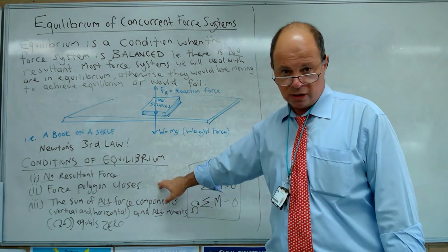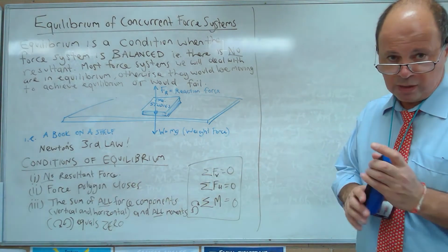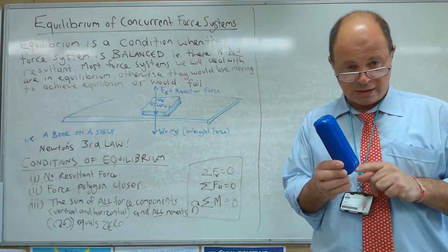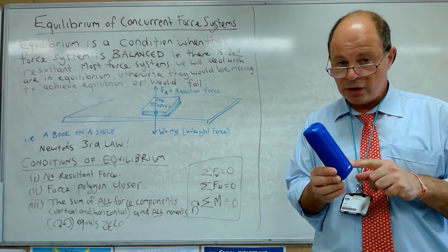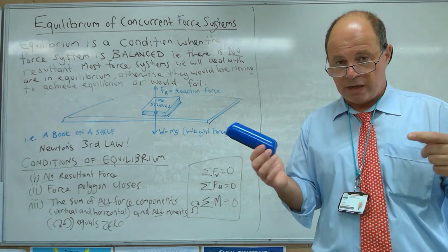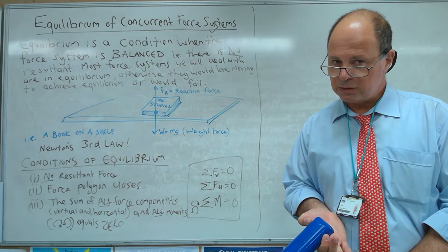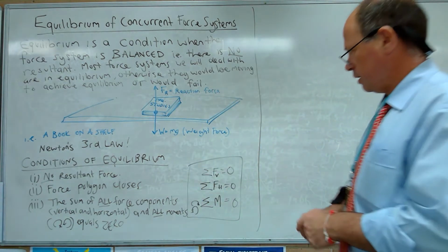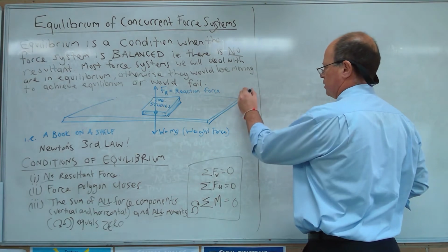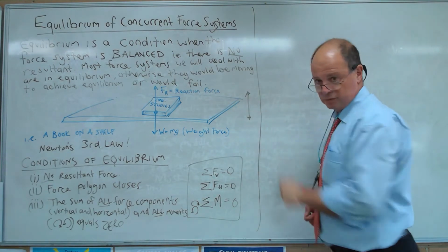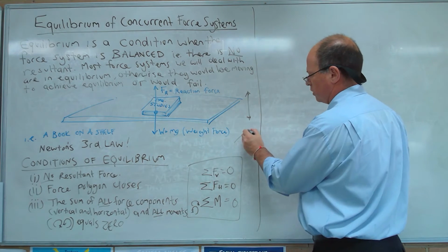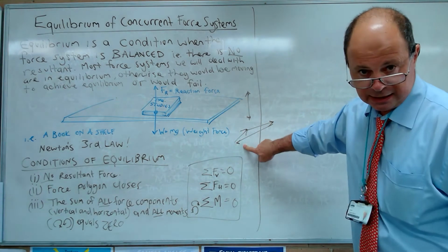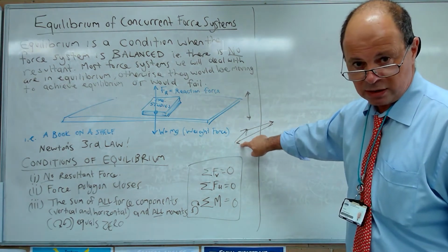The force polygon closes, so when we add our vectors, and we've done addition of vectors, you will return to the starting point when you add them. If you don't return to the starting point and the system is in equilibrium, it means you've missed a force, okay? So in this instance here, one goes up, tip to tail, one goes down, and therefore the system is closed, okay? If you had a more complex system where you're adding, if you got all the way back to the start, we know that there's no resultant, okay?